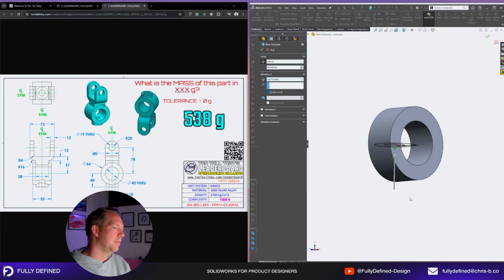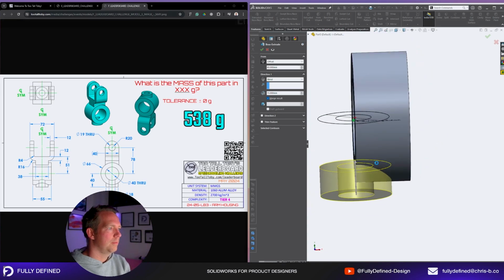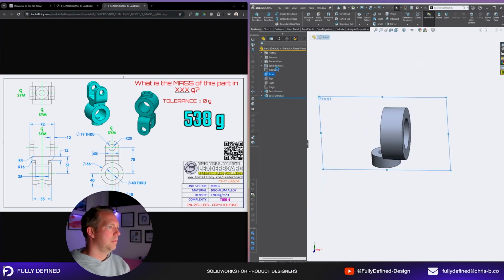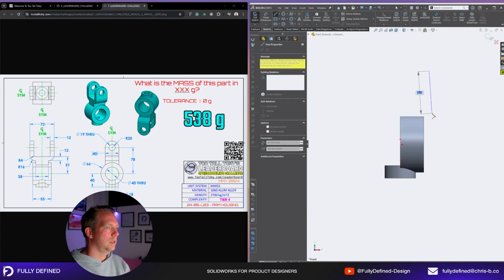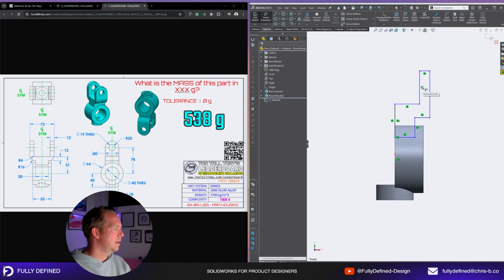up to next. And that up to next won't work because we haven't mirrored yet. So I might just go blind and make it 15. Just going to make sure it merges. Yep, okay, that's okay. And then the top shape, I will do it from the outside. So we're going to go on the outside, fill it later, straight down, in. All right, and then dimensions with a radius. Radius 16. 12 mil thickness, 4 mil on the outside.